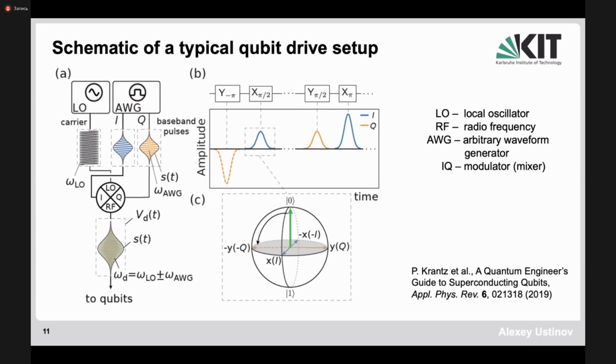So in a way, in the phase space, it shows the vector of the signal, such that it starts from 0, has the amplitude of the wave transmitted, and then the phase is associated with the orientation of this vector around the origin. So if the phase is preserved, then it's pointing in a particular direction. And here we project the signal on two different orthogonal directions, I and Q, which can be amplitude and phase, or any combination of amplitude and phase shifted by 90 degrees.